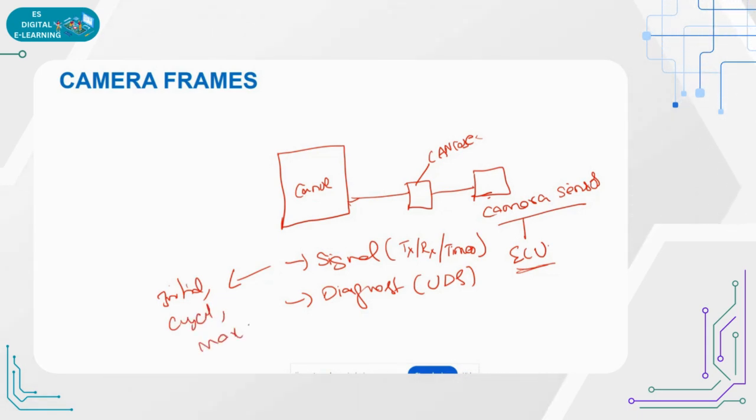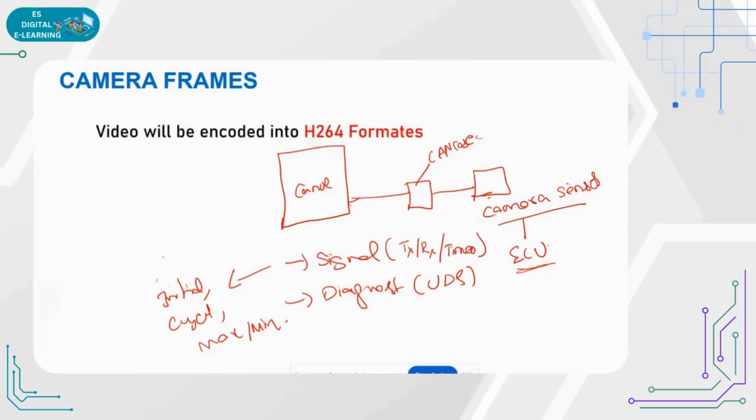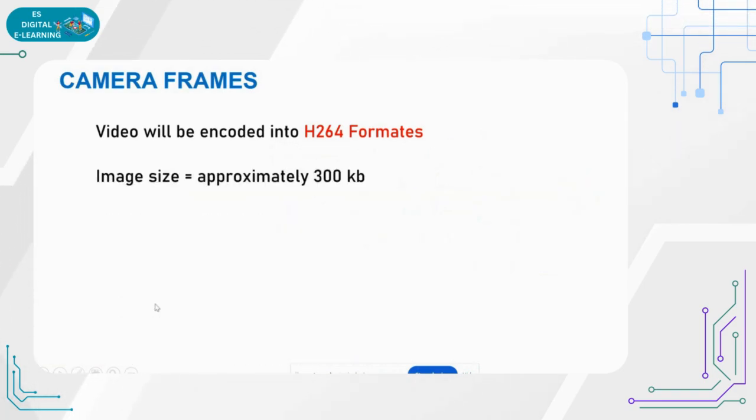All of this we will be doing as part of signal testing. Is it clear? This is how you do it on the HIL bench, and this is part of the open loop bench setup, open loop system, where you are doing single ECU testing. Hope you are clear.